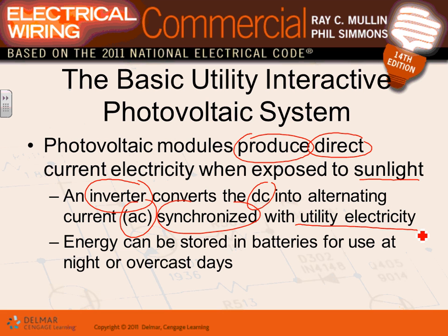the utility. Not only do you have to convert, the interactive inverters have to do two functions. They have to convert the DC into AC and synchronize it with the grid, because if you don't synchronize it with the grid, you will blow up your system. So then you synchronize it with the grid. Then, when you synchronize it with the grid, either you utilize it in your plant or you can shoot it on the transmission distribution lines to sell it to Xcel with certain agreements.